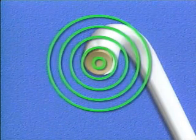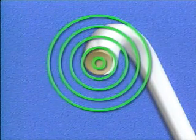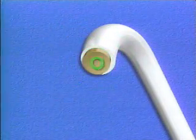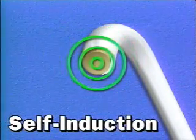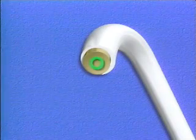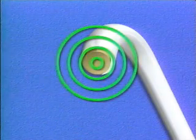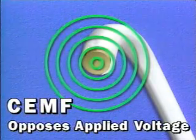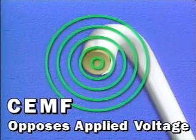Now, while the magnetic field is building up, there is relative motion between it and the conductor because the field itself is moving. Whenever there is relative motion between a magnetic field and a conductor, voltage is induced. In this case, a current-carrying conductor is inducing voltage in itself, so we call the process self-induction. As the magnetic field builds up, the voltage induced in the conductor is opposite in polarity to the applied voltage. This induced voltage can be called countervoltage, counter-electromotive force, or more simply, CEMF. Because it opposes the applied voltage, the CEMF limits current.